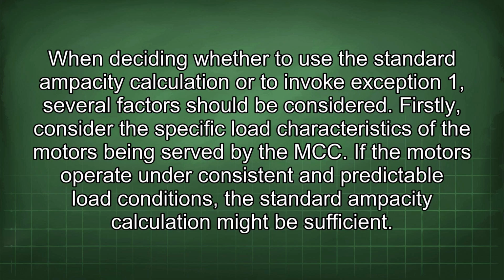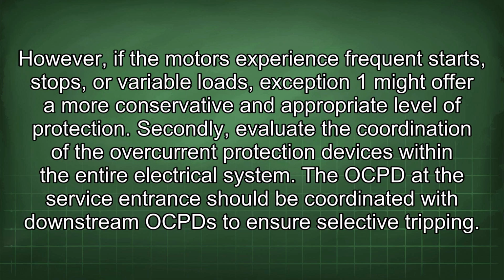equipment. When deciding whether to use the standard ampacity calculation or to invoke exception 1, several factors should be considered. Firstly, consider the specific load characteristics of the motors being served by the MCC. If the motors operate under consistent and predictable load conditions, the standard ampacity calculation might be sufficient. However, if the motors experience frequent starts, stops, or variable loads, exception 1 might offer a more conservative and appropriate level of protection.